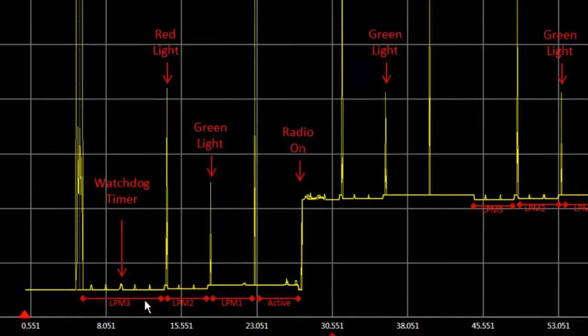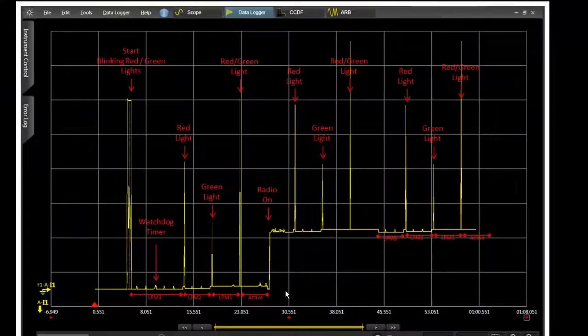And in low power processor programming, you tend to go to sleep a lot, and you use watchdog timers to check to see if you need to do anything. In this particular test, you'll notice that we're actually measuring about 450 nanoamps at these low levels. That's what low power mode 0 is, low power mode 3. But when we flash a light, we're actually in the 1.5 milliamp range.